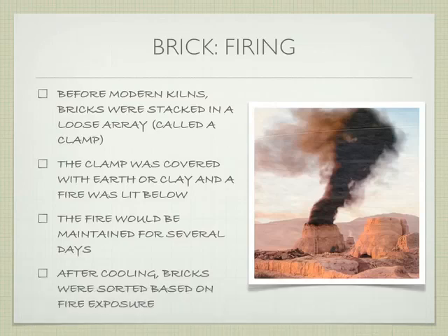So if we're going to fire the brick, we've already kiln dried it, so we've got some of the moisture out. It's in its final form. We need to then proceed with firing. And so before our modern kilns that were more efficient at this process, what they would do is take all these individual bricks and stack them in a loose array, the idea being that there is some airspace on each side.